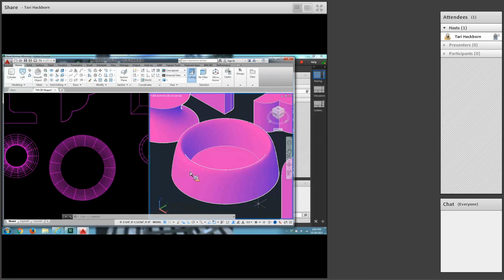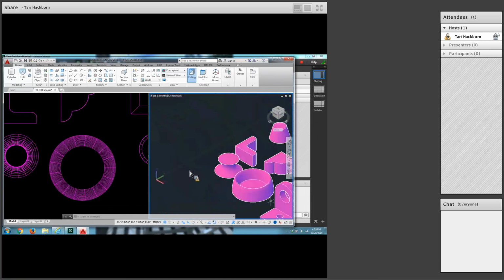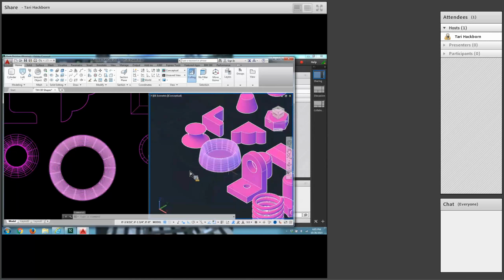The planar surface just ends up making a bar. Okay, so let's see here. Where do they put the plane surf? Oh, it goes right here in front of these things, doesn't it? Do they give me a location for it or not? Nope, pick the lower left corner in the approximate location. You can just type PLANESURF, and enter.